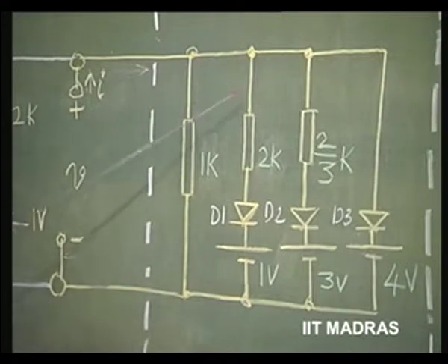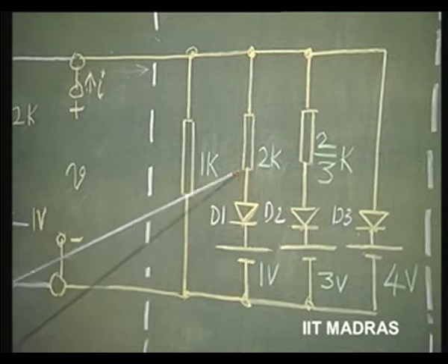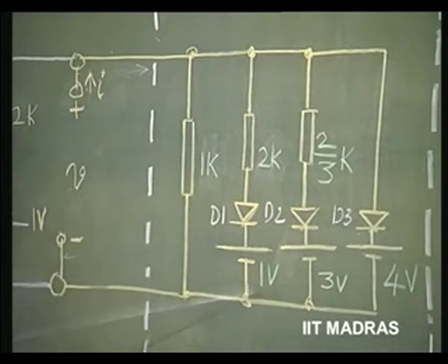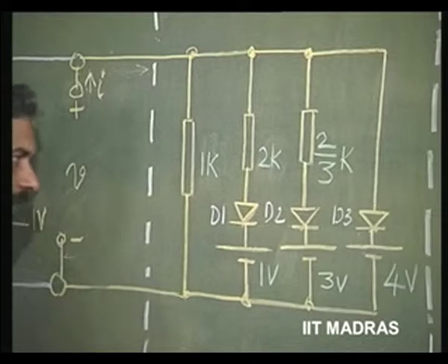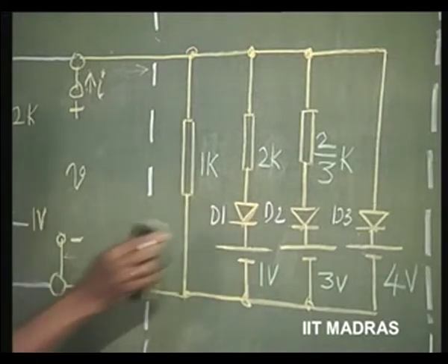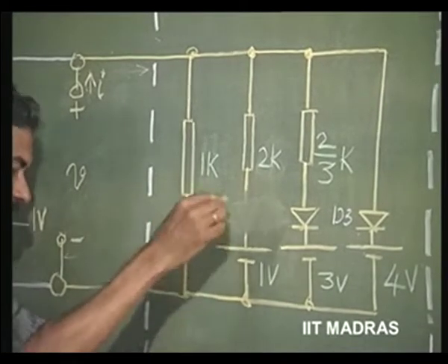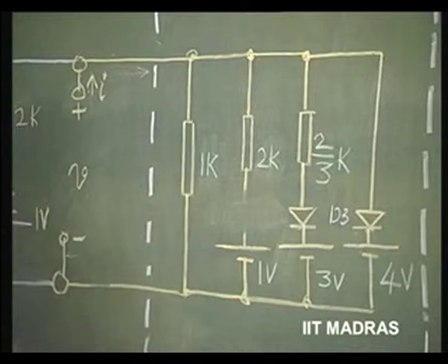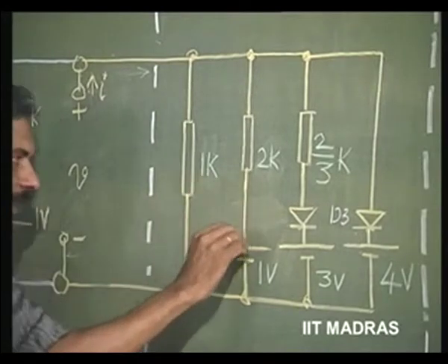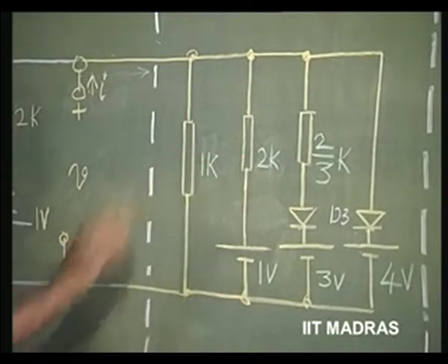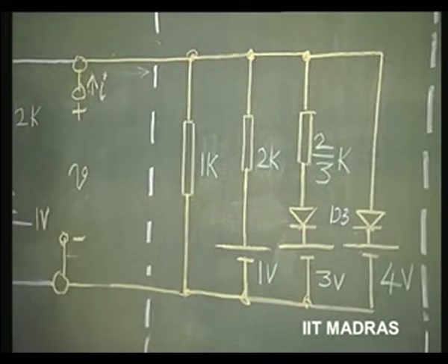So, we are now bringing in these resistors in steps. 1 volt, the moment V becomes 1 volt or greater, this resistance is coming into picture, and therefore, this is a short for that. So, we can just say that this is going to be replaced for that range above 1 volt. You have to solve the equation this way. This 1 k is coming in parallel with 2 k. So, this is a short.